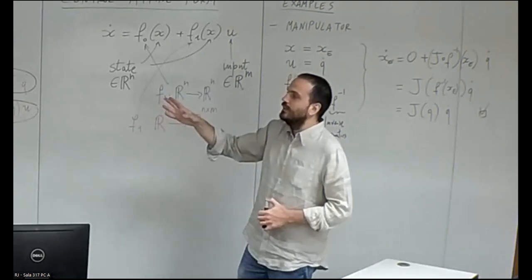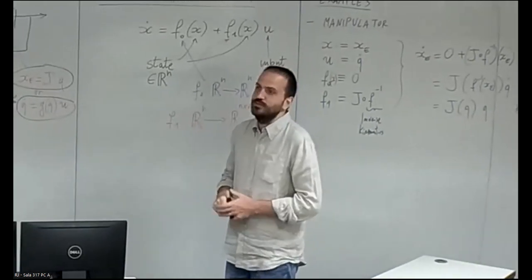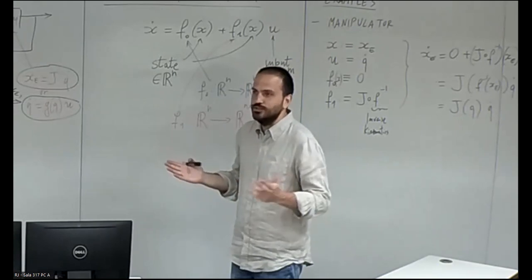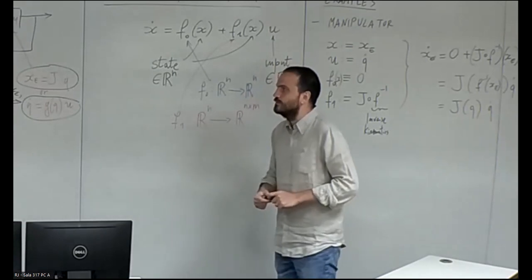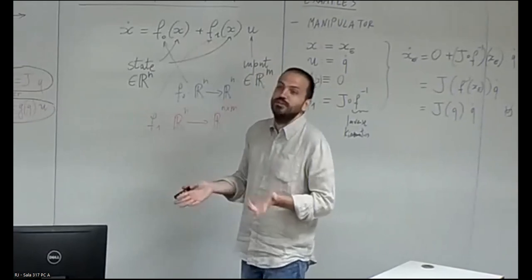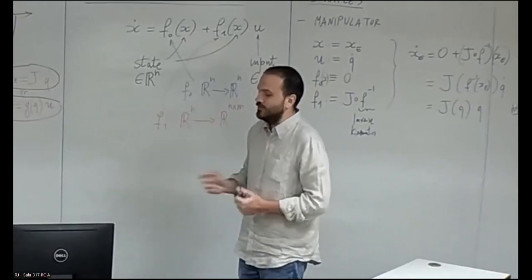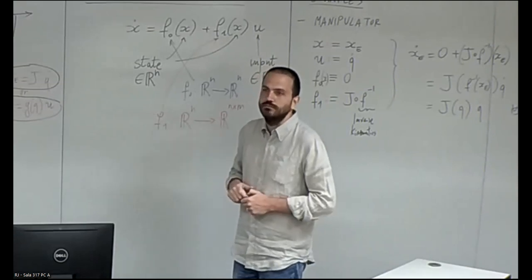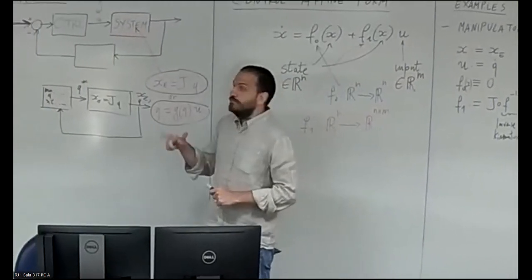In this case, it's like radio controlled vehicles, which are very light. The mass is very small, the inertial effects are small, and the motors are extremely powerful compared to what they need to do. So if you just remove the acceleration input, they will stop immediately. Or that's the case for a very slow car.